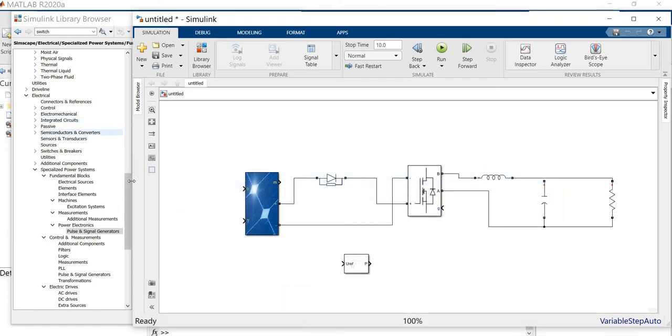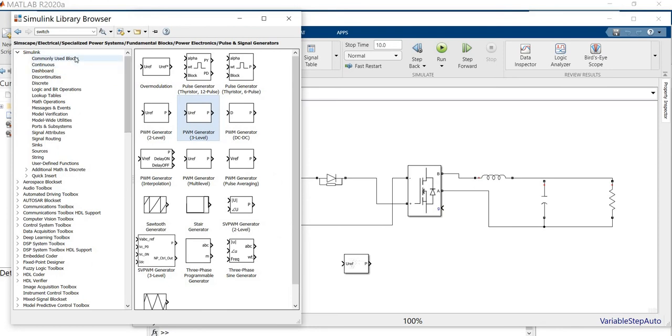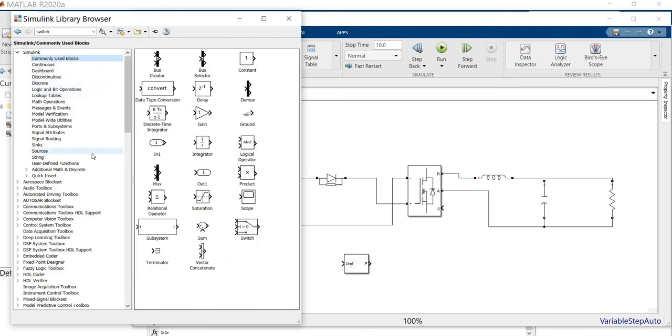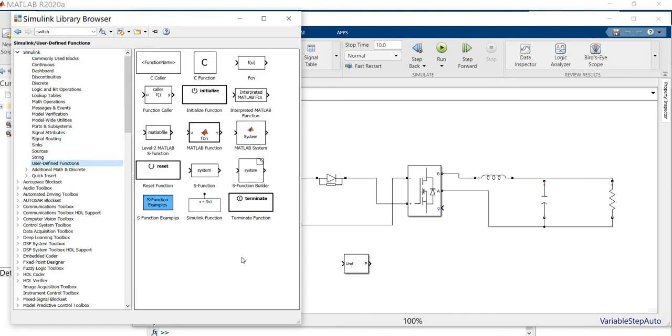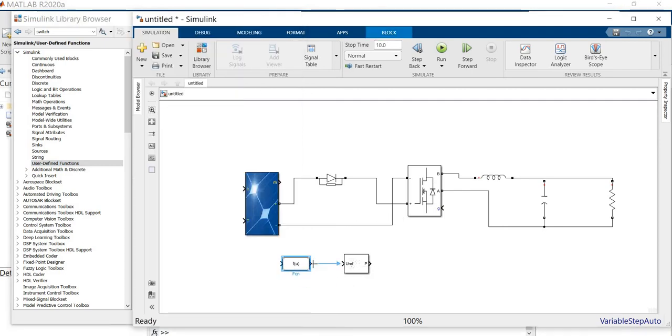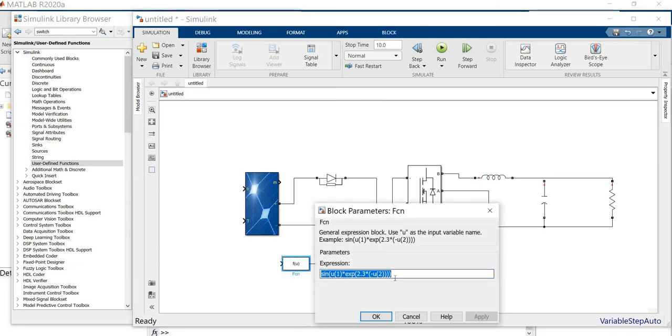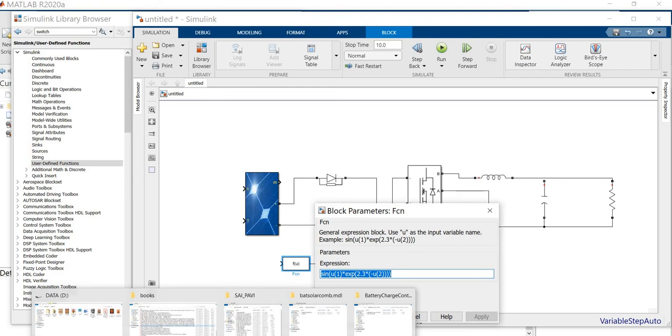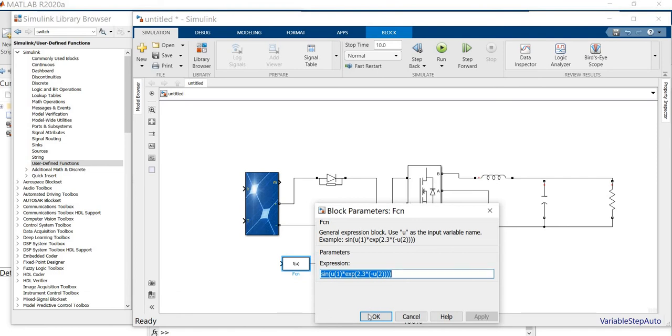So here, how can I set this sine wave? That is the subsystem modules which are available here, the user defined function, which is available in MATLAB. I am also going to select this. I am going to drag and drop and then connect the system. Here I want to feed the same equation we are developing, sin 2 pi f t.